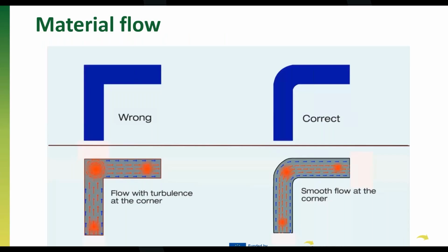I want to mention the geometry because it's really important to understand the material flow in order to design a mold properly. In injection molding, it's quite important to avoid edges and 90-degree angles. Angles are usually smooth in order to allow better flow and avoid problems or gases that are accumulated in